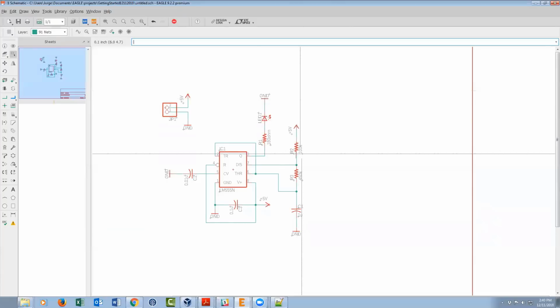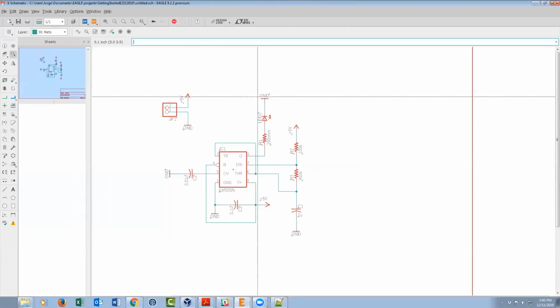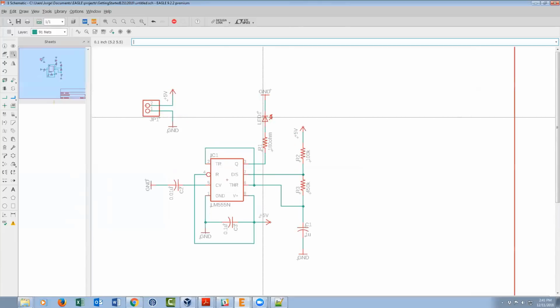The only thing I do want to mention here is the supply symbols, okay, because that we didn't do before I brought in the cook schematic. Okay, design symbols are special. If you notice here, we have 1, 2, 3, 4, 5. We have 5 grounds. Okay. Supply symbols automatically connect to each other, even if you don't draw a net from one to the other, okay? So these 5 grounds, by virtue of being supply symbols, are automatically connected. Same thing happens with the plus 5Vs. These 3 are automatically connected. I don't have to draw nets between them to connect them.